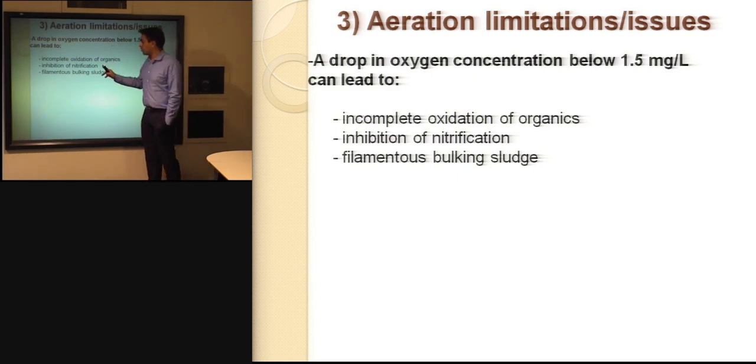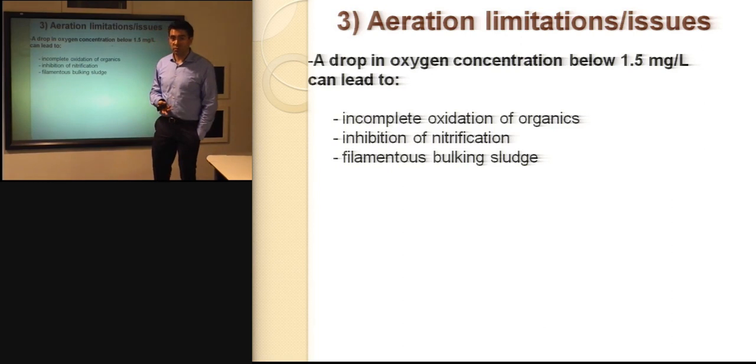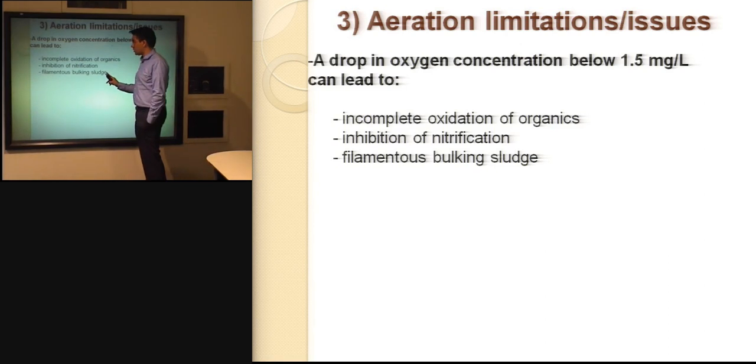It will lead to the inhibition of nitrification, because nitrifiers will not be able to have enough oxygen to continue with the oxidation of ammonia. And that can also lead to filamentous bulking sludge.